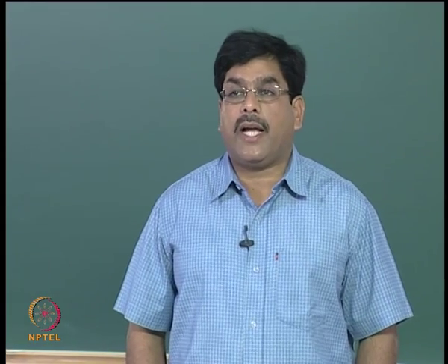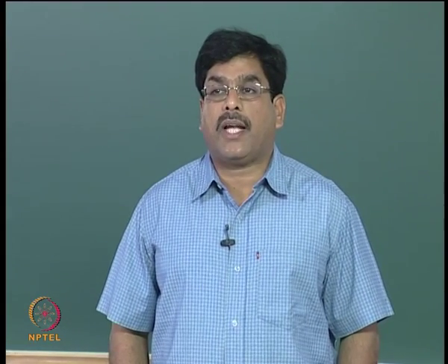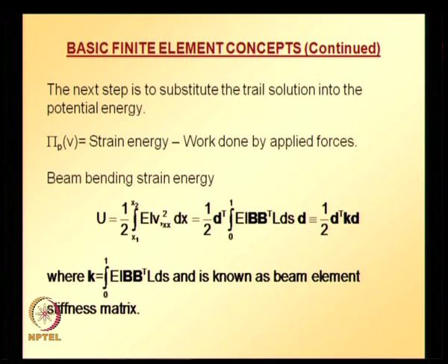Integral 0 to 1 EI B B transpose L ds, and is known as the beam element stiffness matrix. This is a general equation, and even if the modulus of rigidity is not constant, this equation can be used and integrated, and we will get the stiffness matrix.